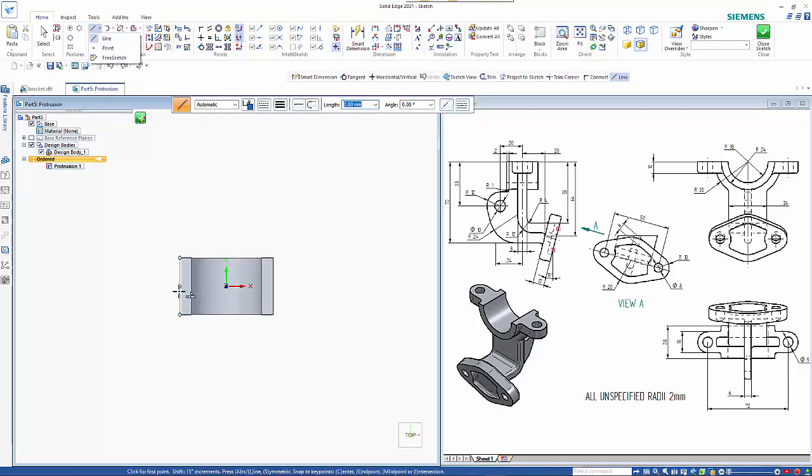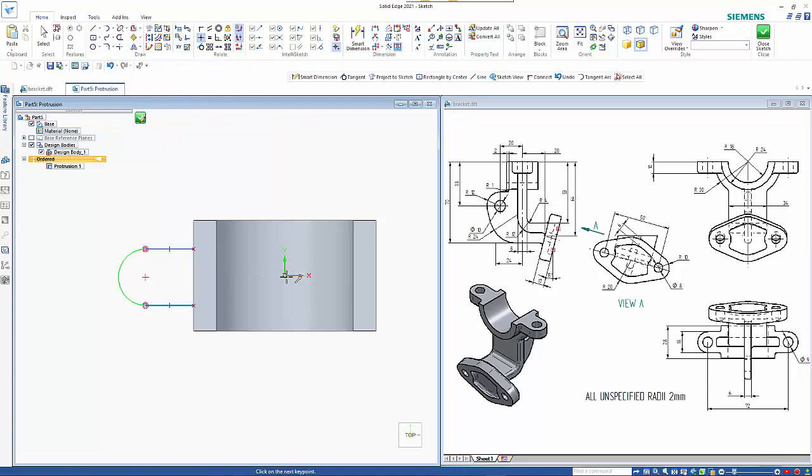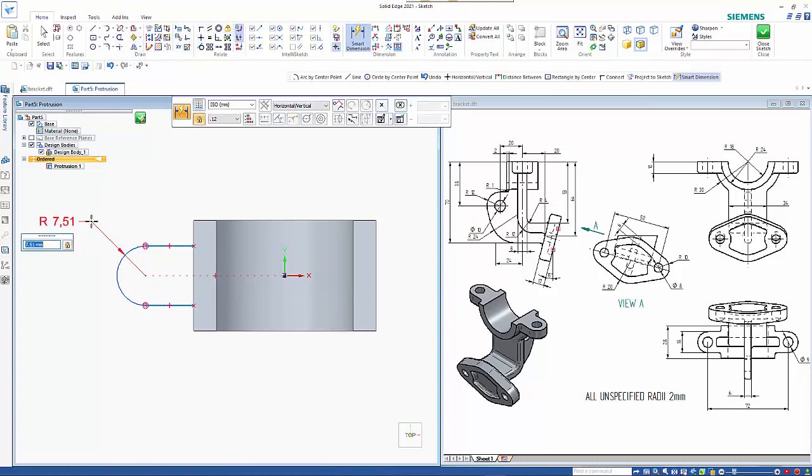So starting here, come out a distance, hit the A key, make sure I come out the right way round, and bring it back to that same edge. First up, I will lock the center of the shape horizontally, and then add some dimensions. So this was 9, and the distance from here to that center plane was 36.